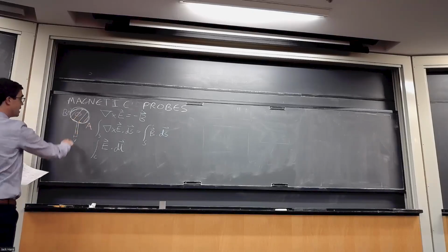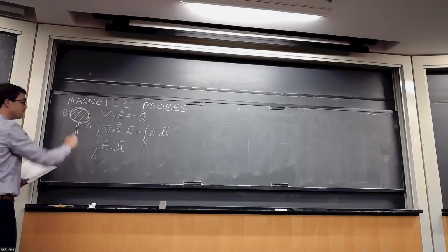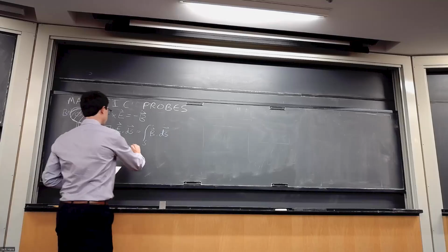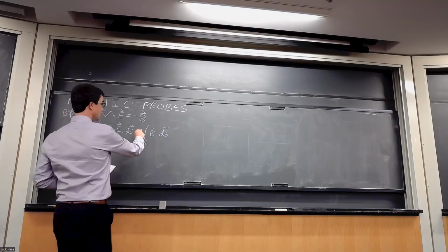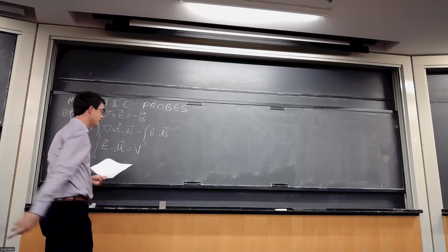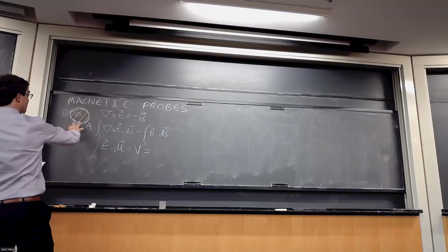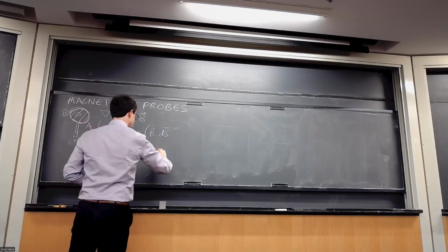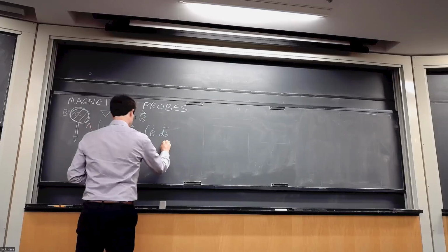We're not going to measure it right here. We'll attach these with cables to some digitizer or oscilloscope out here. So there'll be a potential difference around this loop. We'll call that potential difference V, and that's simply going to be equal to the integral of B dot, dotted with dS here. We've already said that the area of this surface is simply A, so we'll just write that as A, and then we'll write this as B dot here.